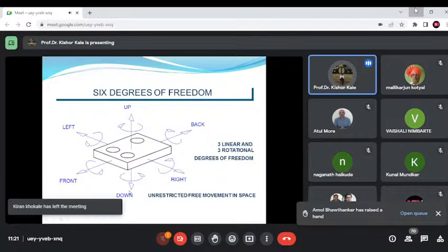So you can see the primary datums come into this. Accessibility, shafts get in the way. Whether a datum is required for the shaft, yes, we require datums for the shafts. So the primary datum review: the primary datum chosen must ensure precise measurements. The surface established must produce consistent measurements when producing many identical parts to meet the required specification. That means functional relationship, accessibility, and repeatability would be there for the primary datum.